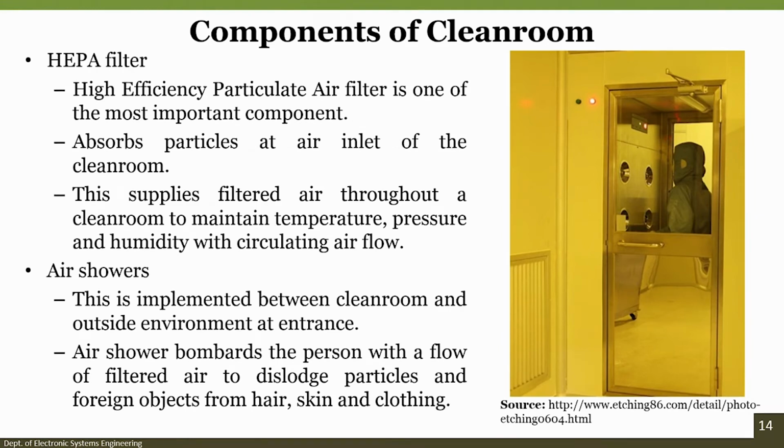Now if you want to create a clean room, the question should be, how can one create a class 10 or class 100 kind of clean room facility? The answer is by using a filter called HEPA. HEPA stands for high efficiency particulate air filter, and it is one of the most important components of the clean room. The HEPA filter works by absorbing the particles at the air inlet of the clean room, and this supplies the filtered air through the clean room to maintain temperature, pressure, and humidity.